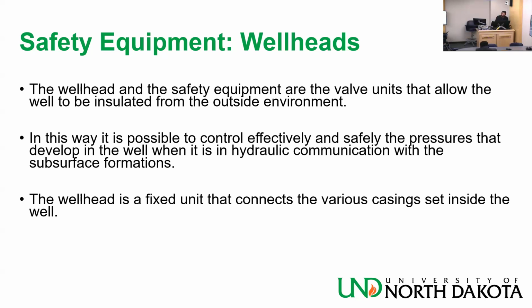The wellhead is a fixed unit that connects the various casing strings set inside the well. So this is where they all anchor. We said casing makes it all the way to the surface. So where do they anchor on the surface? On the wellhead. The BOPs are above the wellhead. They are installed on the wellhead. Remember, there is always a wellhead from the drilling until the production.